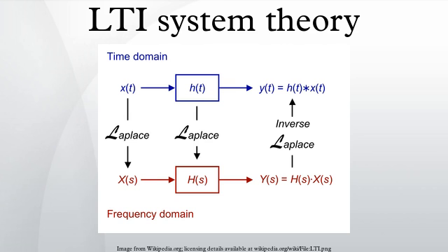One can look at the modulus of the system function H(z) to see whether the input is passed by the system, or rejected or attenuated by the system. Examples: a simple example of an LTI operator is the delay operator. The Z transform of the delay operator is a simple multiplication by z^{-1}. Another simple LTI operator is the averaging operator. Because of the linearity of sums, it is linear. Because it is also time-invariant, it is an LTI operator.